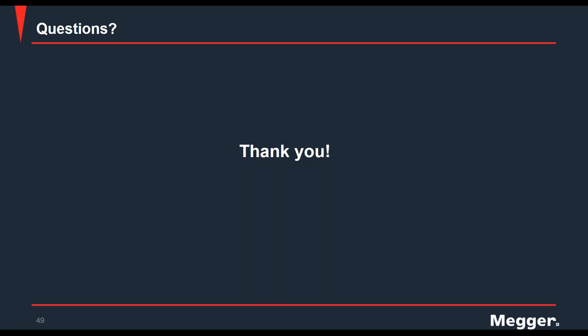So in a typical test, you have to leave one side ungrounded so you can perform the test, and then obviously ground it again to disconnect your leads. Some of our DLROs, like Samir explained, have the capacity of performing the test with both sides of the breaker still grounded, right? So that's what we call the dual ground technology. Thank you.